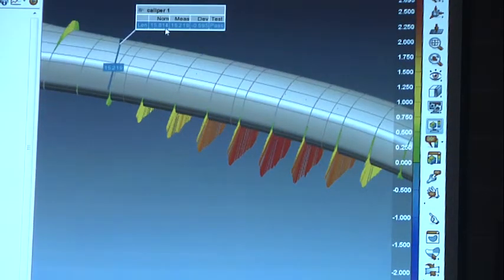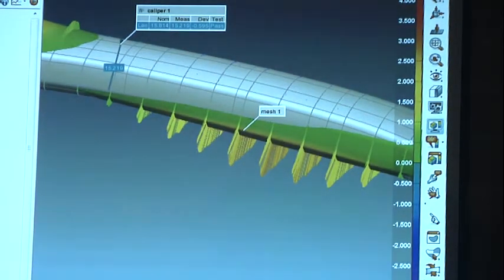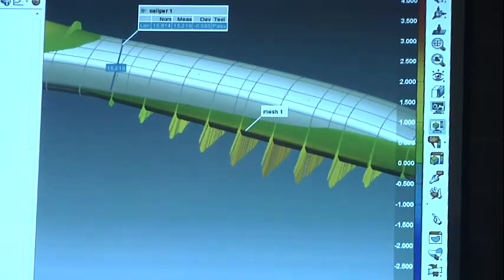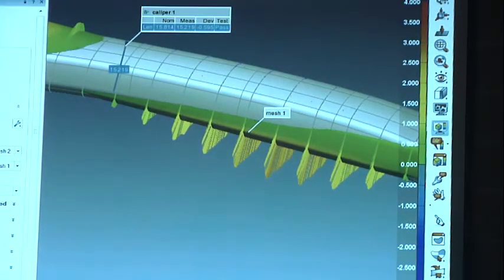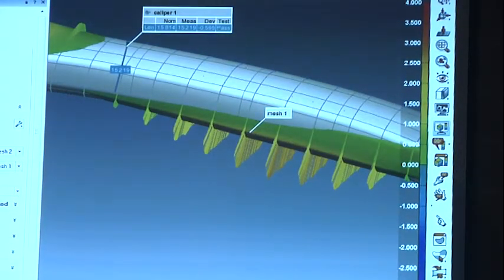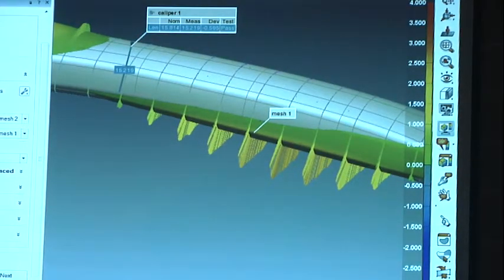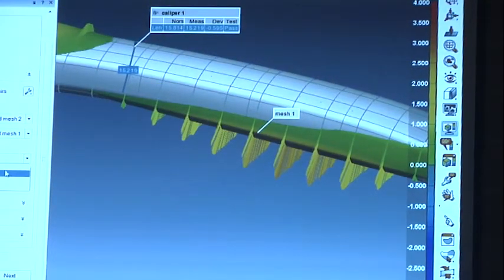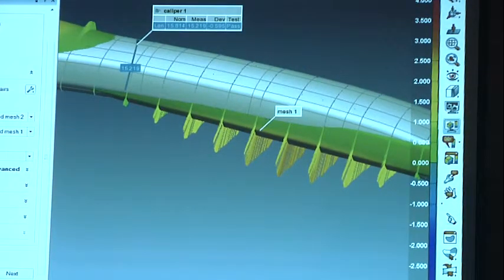So it's 15.219. If I change the best fit between my 2 data objects, between my 2 scan meshes, the unified mesh is fully parametric as well. So if I change the parameters, let's say I'll use all the points this time, it will update the best fit. It will change the relation between my 2 halves of the models, and it will reunify it and update everything.